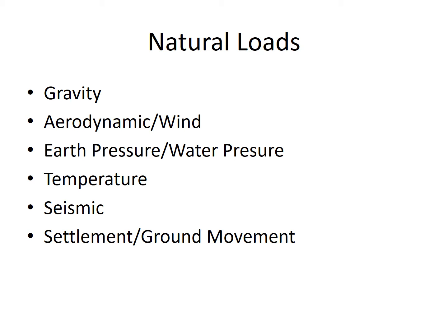So again, the gravity of all the roof structure, the walls, the ceilings, the wall coverings, they all have mass, and under acceleration due to gravity, they exert a force or weight onto the structure, which, as we saw in the previous slide, has to find its way through a load path down to meet a reaction.